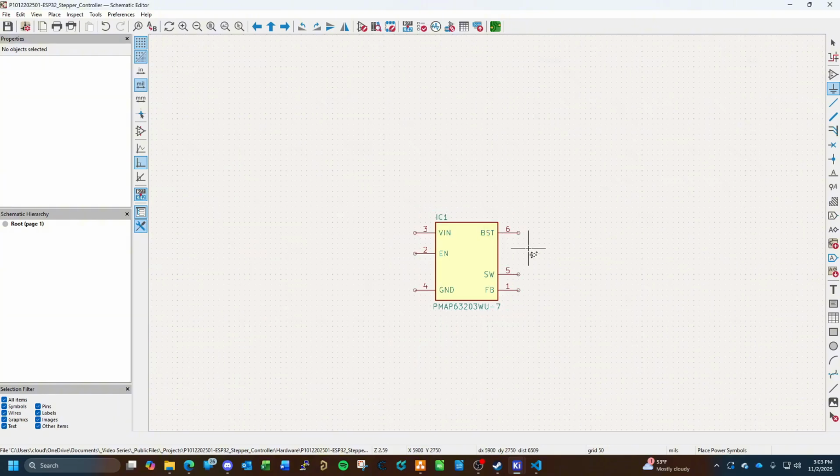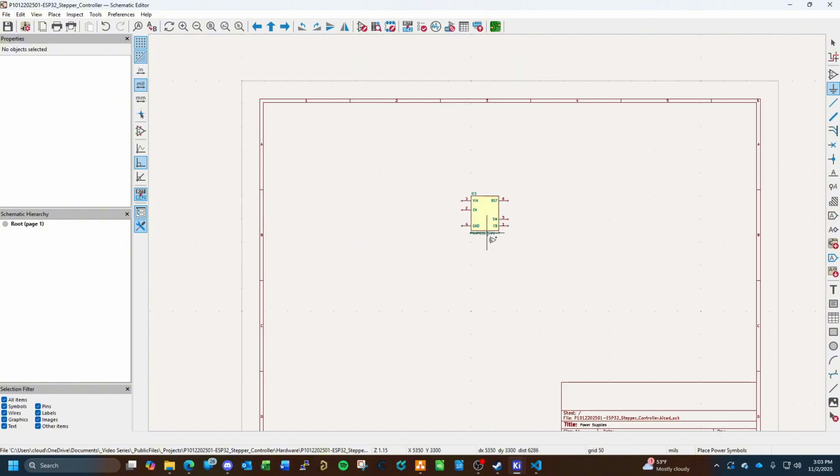But we have our first part in here. We've started the schematic capture. So we started creating our library files. We created our first schematic symbol, where we didn't create it, we just imported one that was already created by the manufacturer. Those are usually the best way to go. We just modified it to suit our design flow and everything like that.